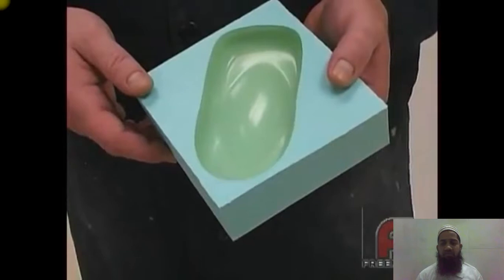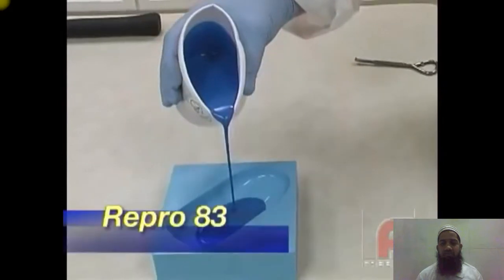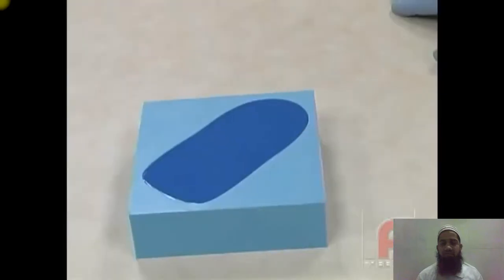As we pour our thoroughly mixed repro into our mold, we typically like to create a smaller stream in order to break the bubbles better. Regardless, given its thin viscosity, bubbles aren't much of a problem with repro, and it's never necessary to vacuum degas repro. After allowing our part to cure for 60 to 90 minutes, depending on the mass of the pour, we can now demold it and immediately begin using the mold to pour another casting.